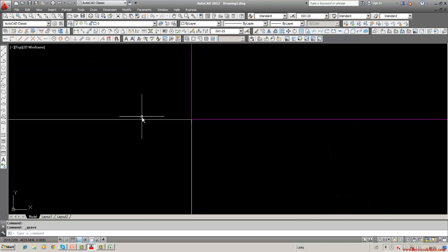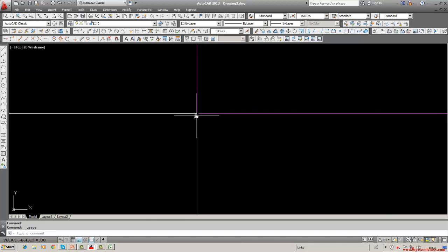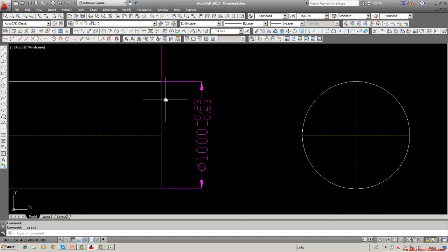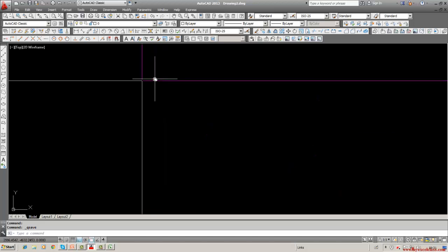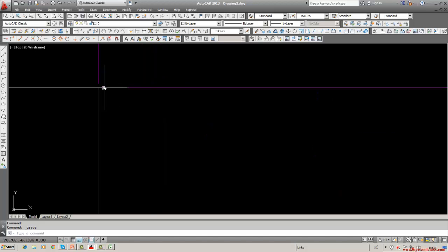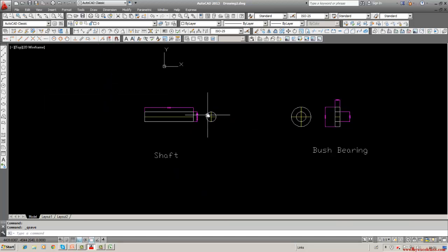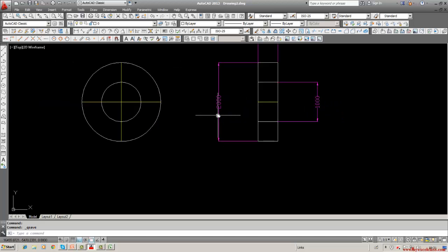And of course, here you can select the gap and all. Last time I explained in dimensioning, all that you can select as you wish, 1 mm or 2 mm, the gap between this edge point and this point. Here it is very close, but you can make it bigger by selecting that in the menu. Similarly, here the dimension has to change. This bore only we have to tolerance. How we are going to do it, let us see.